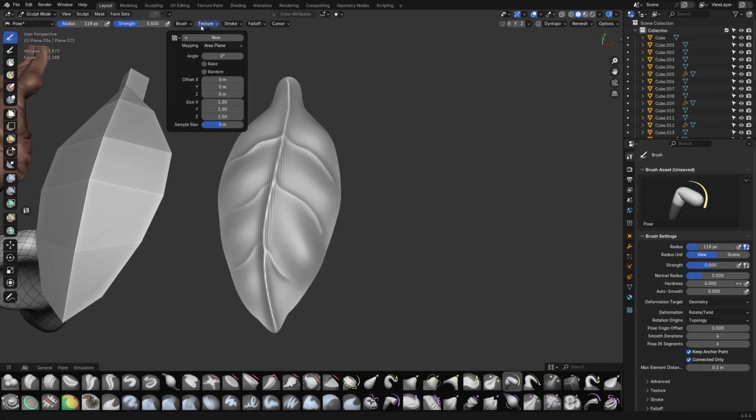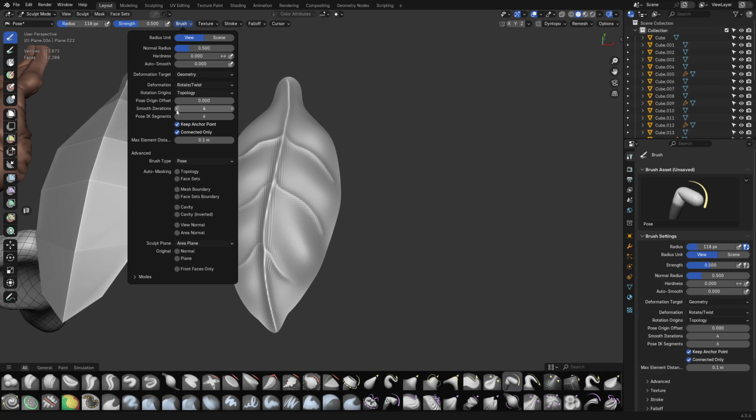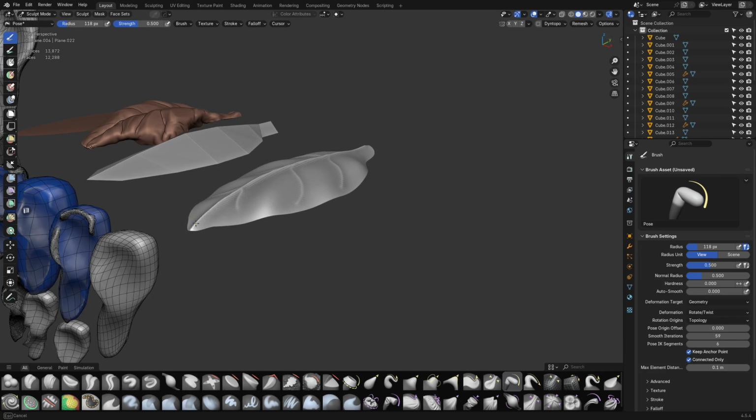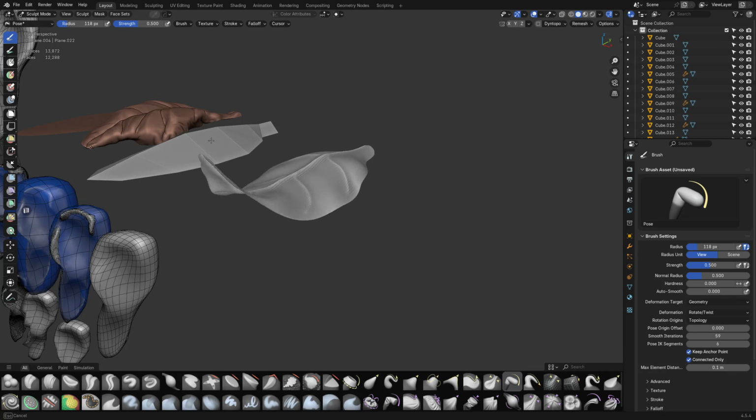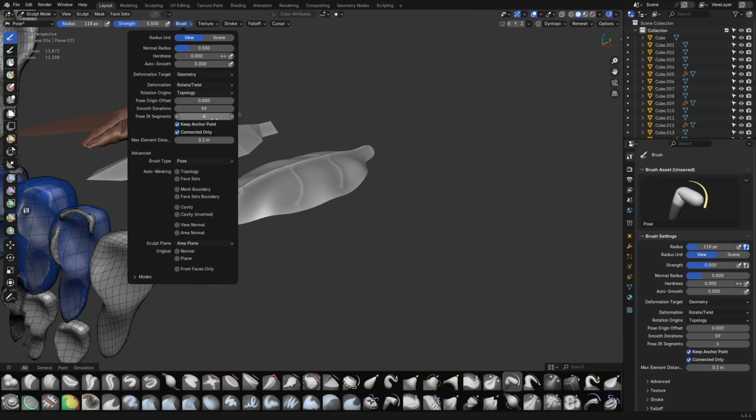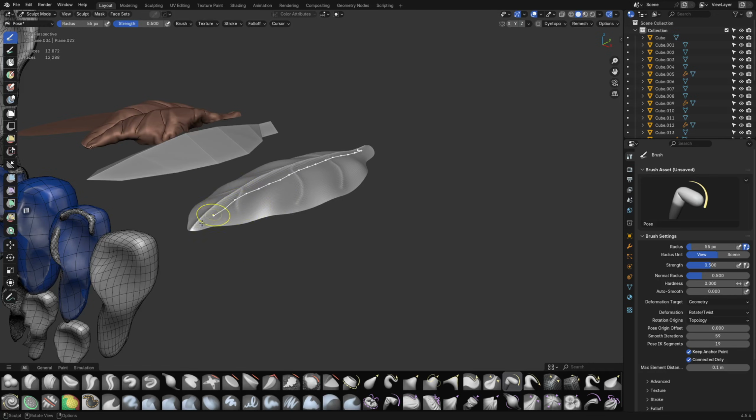You can actually tweak it a little bit more by changing the iterations here. Smooth them. You can turn that up quite a bit actually, and it'll just keep it from being so sharp when we do the bend. But the segments are still there. They're not going anywhere. So I don't even know how many segments it'll actually let you use, but probably a lot, right? And I haven't really tried that before.